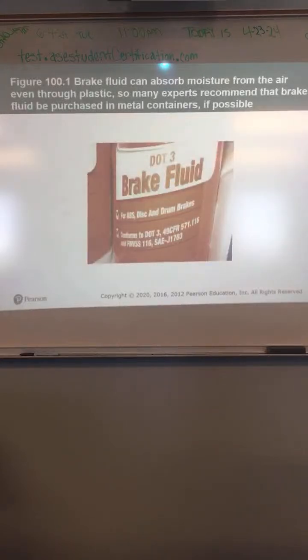We talked about this a little bit yesterday, but one of the reasons that you should do a brake flush on the car every couple of years, or every 20, 30,000 miles, is because brake fluid has the tendency to pick up moisture, okay? So if you get a little bit of moisture in the brake fluid, or let's say water, because it's hygroscopic, right? Water boils a lot quicker than brake fluid does, right? Brake fluid gets hot. So if the system has moisture in it, the brake fluid is not going to be as effective, because when the brakes get hot, it could cause the brake fluid to actually boil, okay?